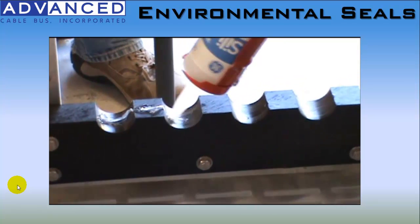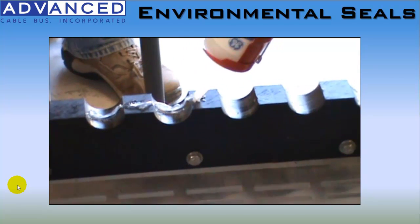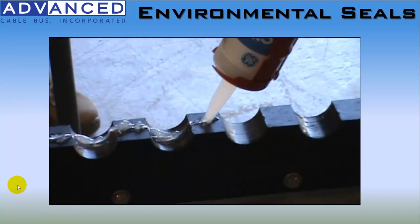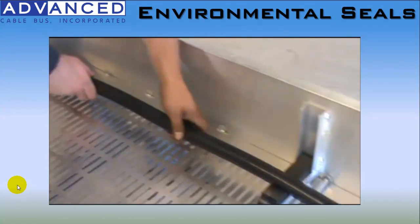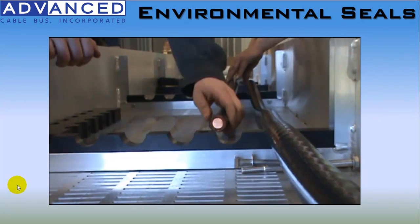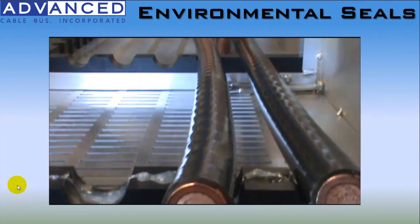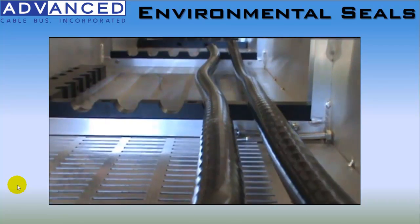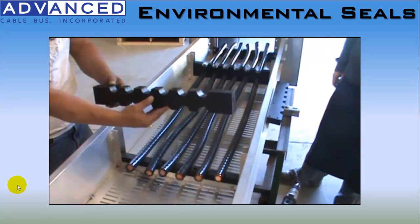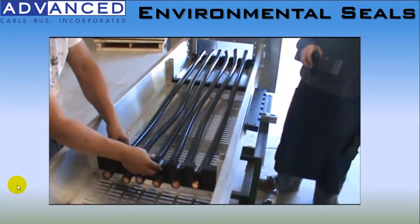Starting from the bottom block, line the center of the support block with silicone sealant. This will ensure that when the cable passes through the seal block, there is a weather-tight seal around the cable. Once you pass through the entire complete row, you then put in the next layer of support blocks and the next layer of seal blocks.